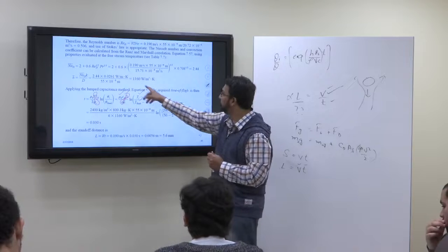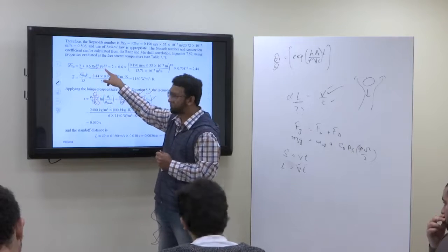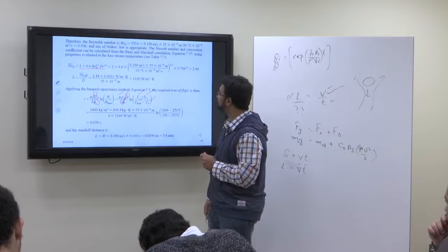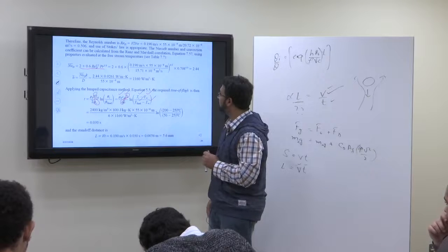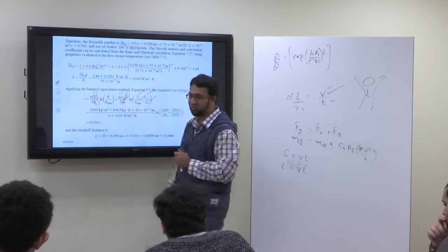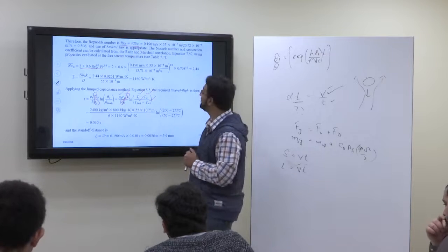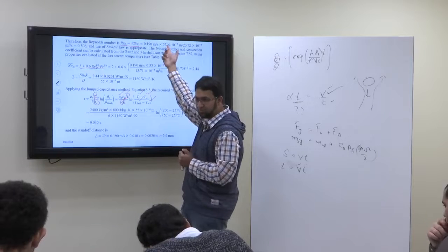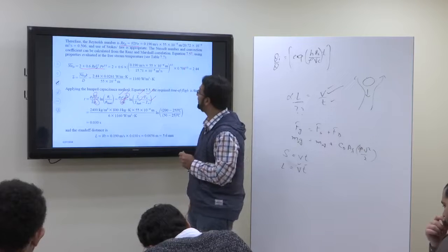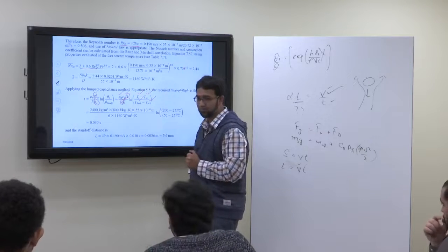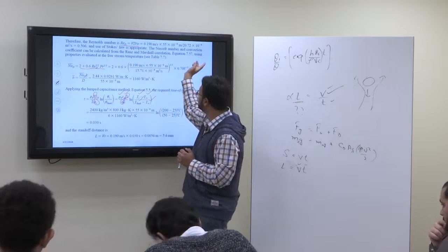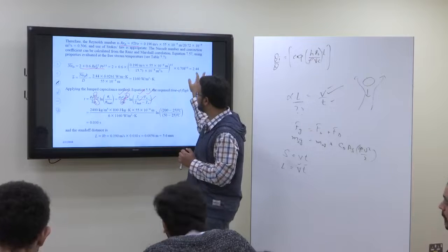So now we use this equation. It was the Ranz and Marshall equation. Substitute all the values here. Before that we find out the Reynolds number. Reynolds number is Vd upon mu. The velocity is the terminal velocity, the diameter is given, divided by mu, the properties of the air that we are going to use here. And use of Stokes law is appropriate. Then substitute all the values, you get the Nusselt number.